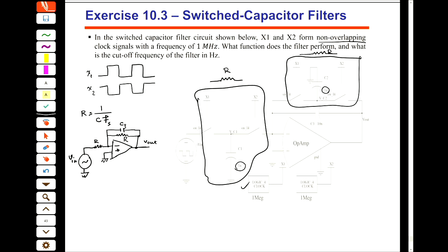And then the transfer function of this, V out divided by V in equals minus, alright, one thing that I forgot, this one is equal to 1 nanofarad, 10 to the power minus 9, and the frequency of the clock is 1 megahertz, 10 to the power 6, and it is 1 kilo ohm. Okay, so this is equal to minus Z2 divided by Z1.